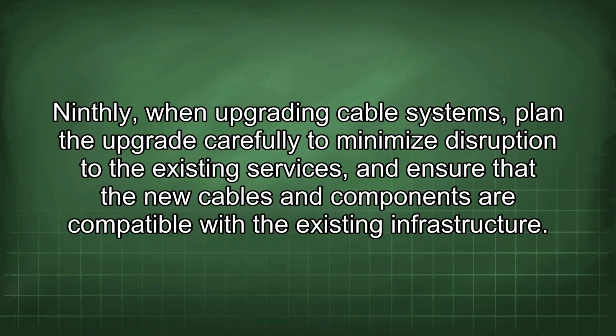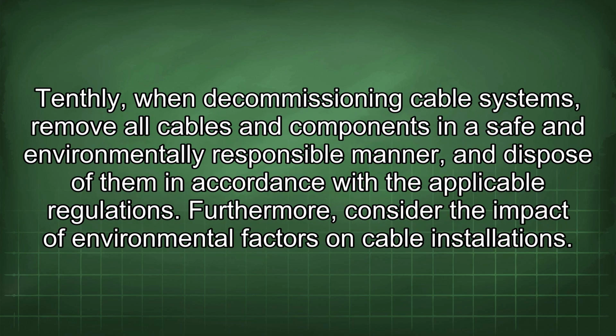Ninthly, when upgrading cable systems, plan the upgrade carefully to minimize disruption to the existing services and ensure that the new cables and components are compatible with the existing infrastructure. Tenthly, when decommissioning cable systems, remove all cables and components in a safe and environmentally responsible manner and dispose of them in accordance with the applicable regulations.